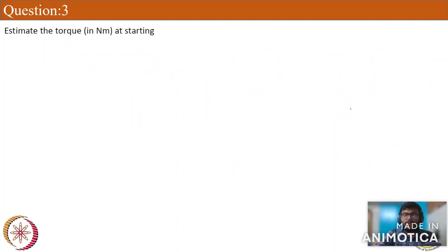That's very less again. Now, estimate the torque at the starting. We haven't even discussed the torque equation yet, but anyway, we will try to solve it by using the torque equation directly. And we know torque is equal to air gap power by 2 pi Ns. We can do this derivation if there is time, or even next week if we are left with some time. I will discuss in detail how we have arrived at this formula, and also what exactly air gap power is.